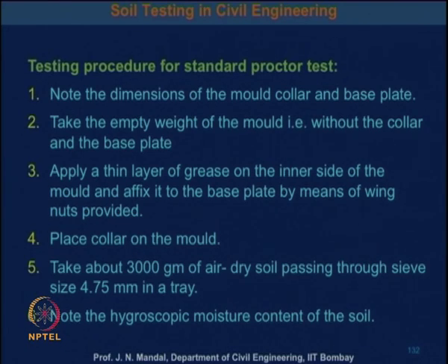Then apply a thin layer of grease on the inner side of the mold and affix it to the base plate by means of the wing nuts provided. Place the collar on the mold.